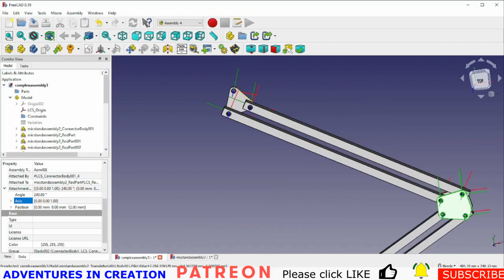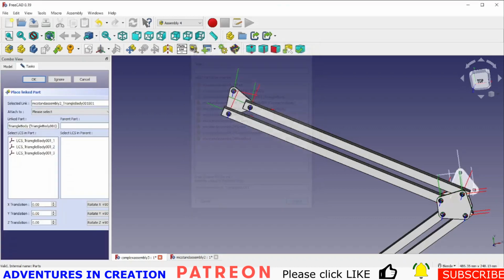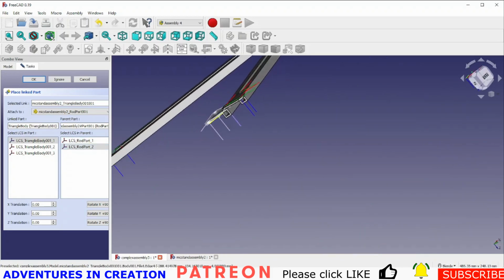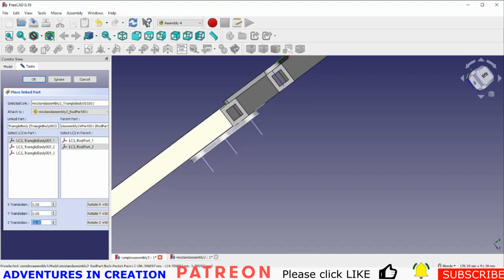And I'll show you one more time. We'll do the same with another triangle part. So my triangle part is here, and I want it to connect by one of its holes. I want it to connect to that rod part, and we'll say on part 2. So you see, if I select part 1, it's at that end of it. Well, I can just change that. That's pretty easy. And then I'm going to need to offset this guy as well. And it's 12, I do believe. Oh no, that was actually overlapping 2, so it's 10.